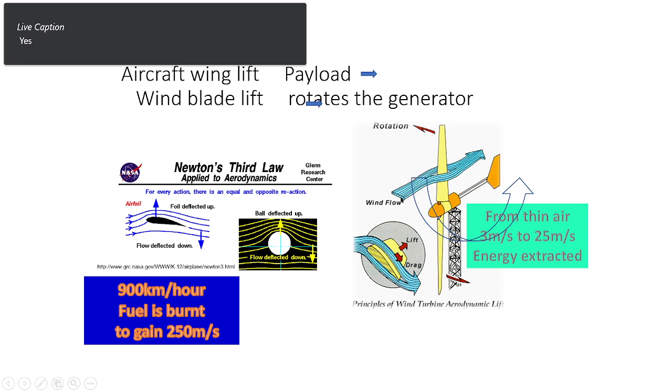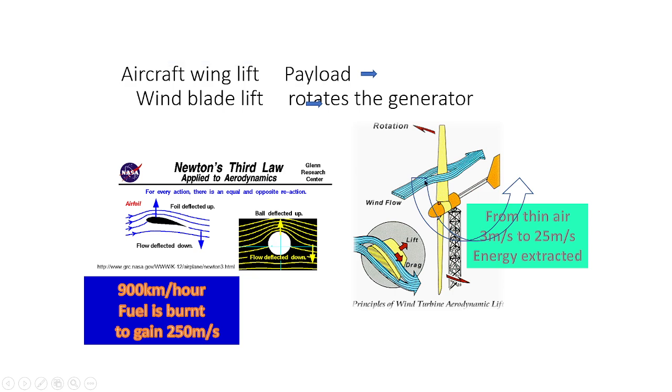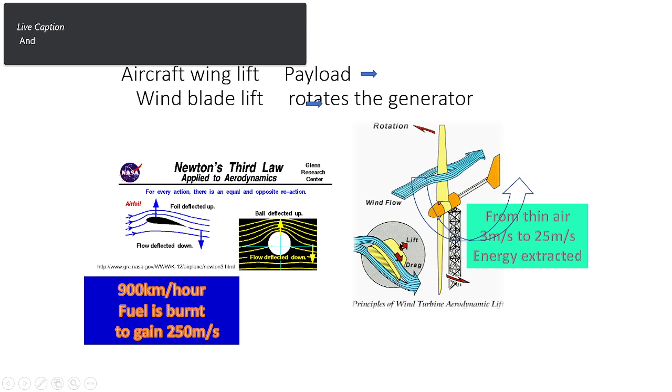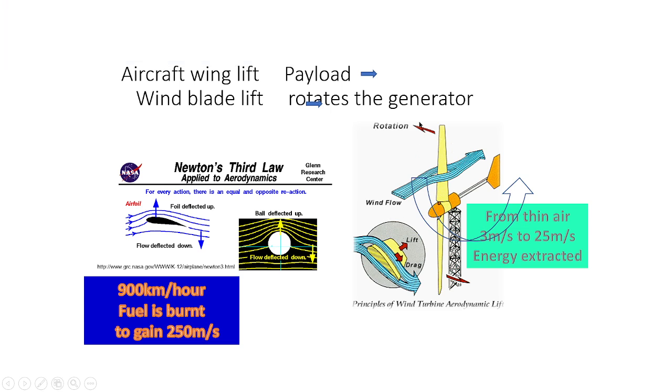The wind flow is the blue line around the blade. So the rotation will happen like this. The lift force should be perpendicular to the wind flow, like this. If you optimize that lift force, that force into this lever arm, the radius, will be the torque, the rotation. It will try to rotate the rotor.